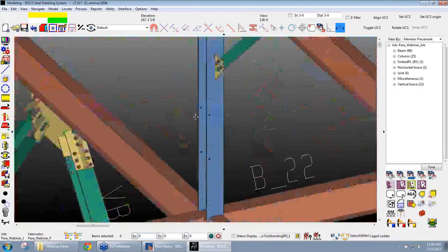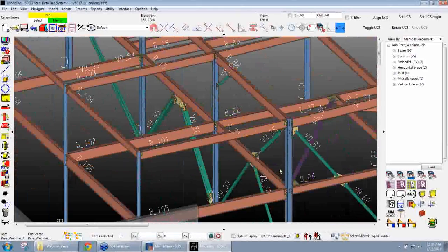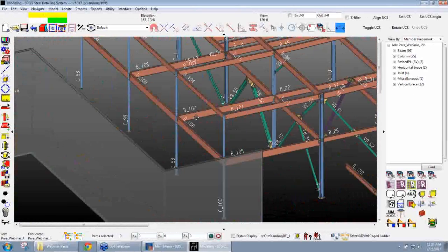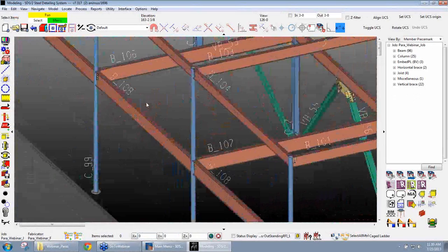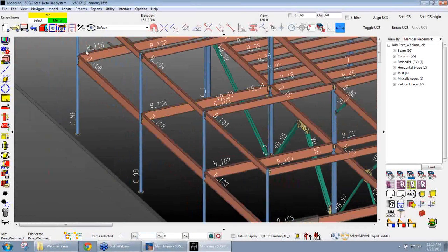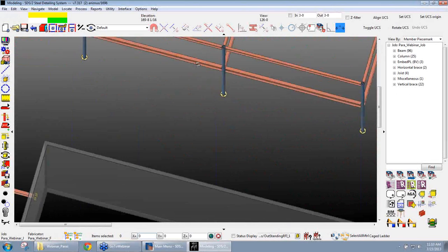This particular parametric will not run on your tubes and your pipe columns. There's another parametric that we can run. It's going to be your column safety tabs parametric if you're running those on a particular pipe or tube column here. So I have a line of pipe columns here that maybe I want to go through and add in some safety tabs to the backside. These columns are rotated 0 degrees, so my B face is going to be here to the near side of me.